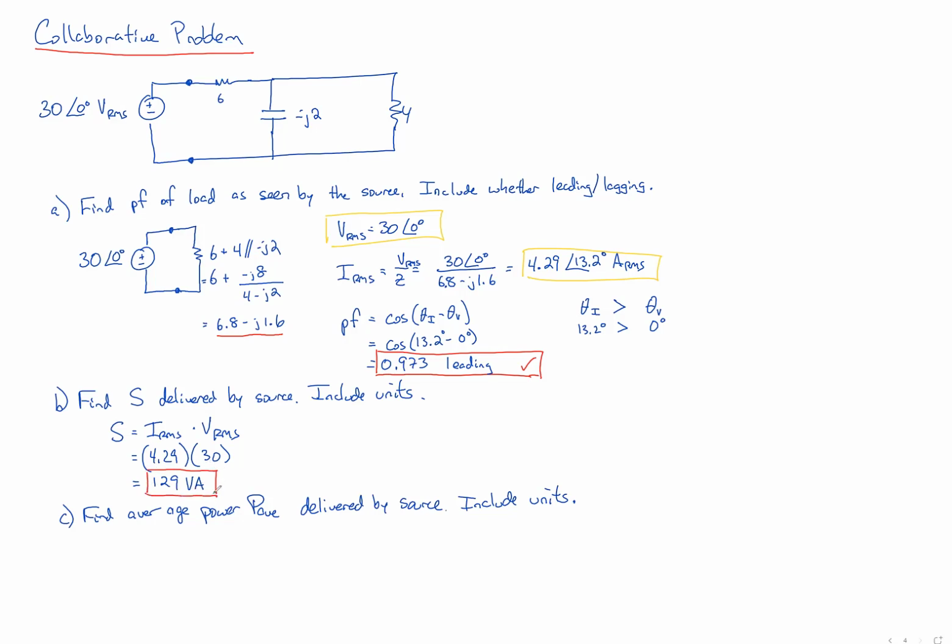Yeah, sort of. But it also would sort of make sense calling it watts, but they want to make it really clear that this is not an average power and it's not an instantaneous power. It's this weird thing called apparent power, which is neither. Nothing is really burning up 129 units of power. It's 129 units of power that are being shuttled back and forth on the power lines. It's much less actually average power that's being used.